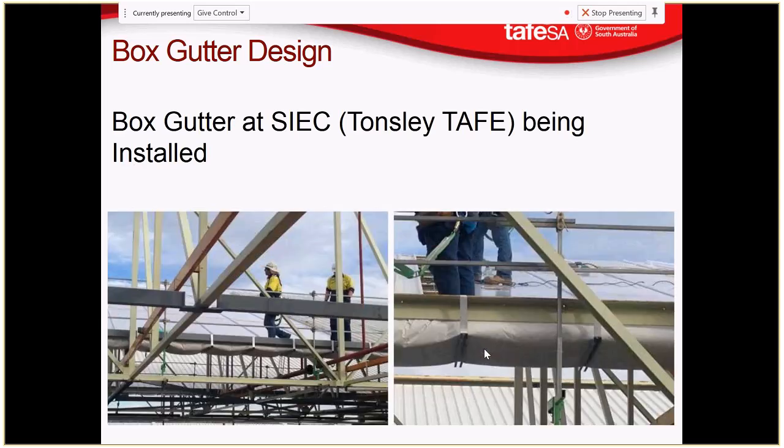I have also seen marine ply used as the base support for gutters as well. But the process of specifying that, I can't shed any light on. I don't know how that's specified. And I think that way of supporting a gutter is better, because if you get any leakage from the box gutter, that water can stay in those channels and go out. Whereas if it goes onto marine ply, it's resistant to water, but you get water staying there and starting to rust out the box gutter, etc.